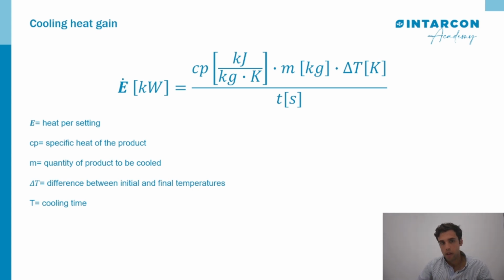So, if we dive into the cooling heat exchange gain that we need to cool that process, it is the product of the specific heat of the product, the quantity of product to be cooled, the difference between initial and final temperature, and the cooling time.